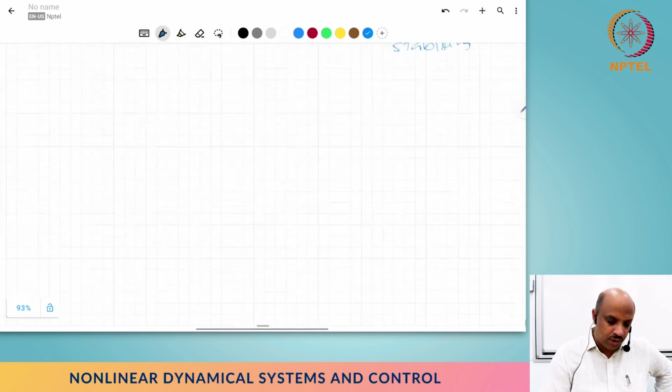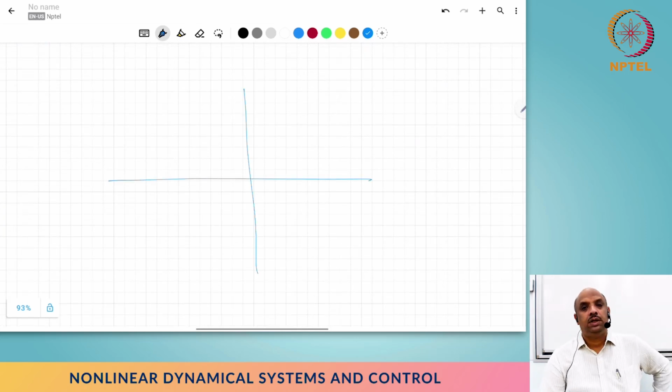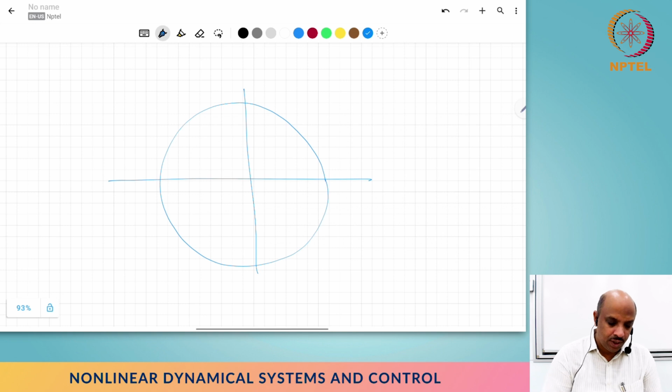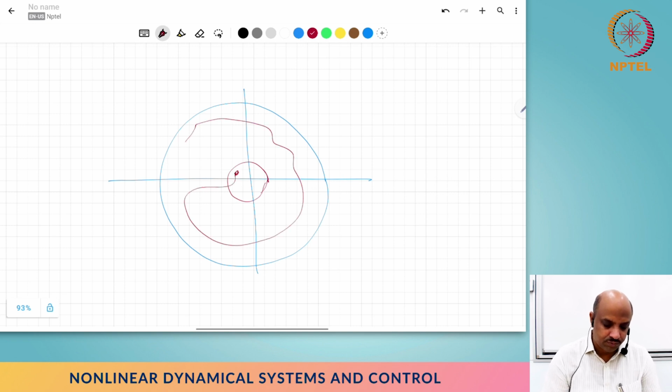Okay, so Lyapunov stability is something like this. Loosely speaking, start close, stay close, right? It's very imprecise in terms of what that says, but a slightly better way of using the English is basically: if I want to remain in a small neighborhood around the origin, can I find a smaller neighborhood, of course, close to the origin, so that if I start within that smaller neighborhood, I will remain in the bigger neighborhood that I chose, right? Let's say I'm choosing this neighborhood, and can I actually find a smaller neighborhood where if I start somewhere here, I'm going to remain there? Perhaps I can go back, but I'll remain within this thing, right?